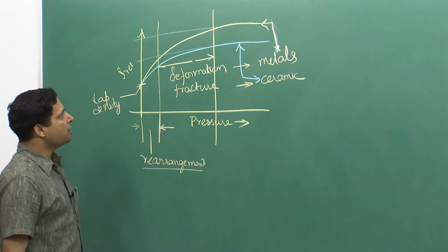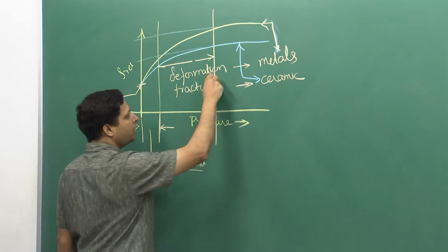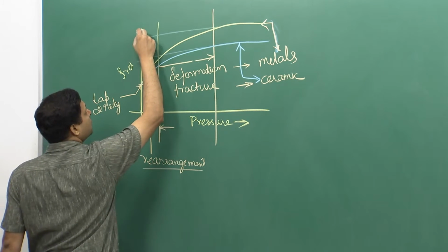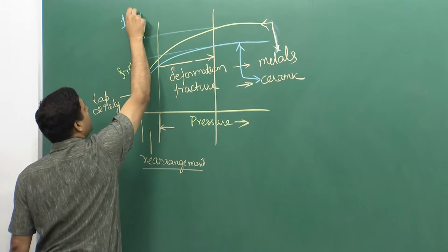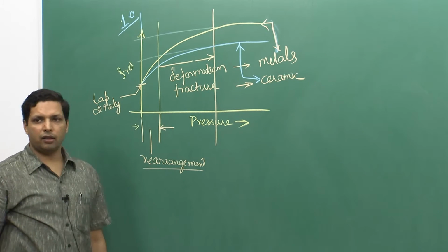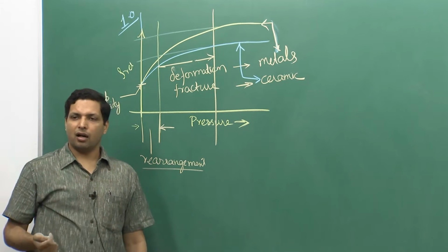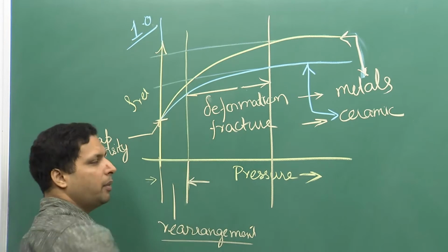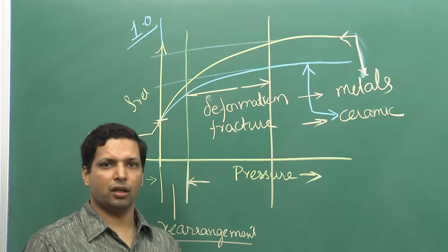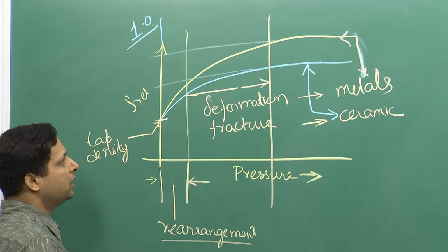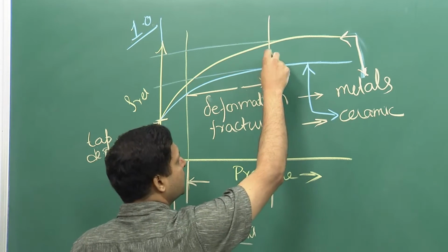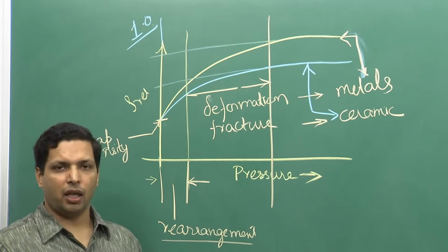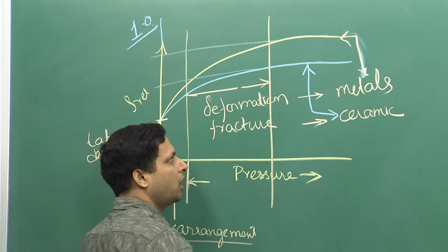And even another important aspect of this is that there is a limit of pressure that you can apply. So, this will be somewhere close to over here, you will have the relative density equal to 1.0, that is the ultimate or the bulk density, but you will not be able to attain that ultimate density just by compaction. That is one important thing to note here. Second thing to understand here is that there is an upper limit of the pressure that can be applied even to get to the saturation range.